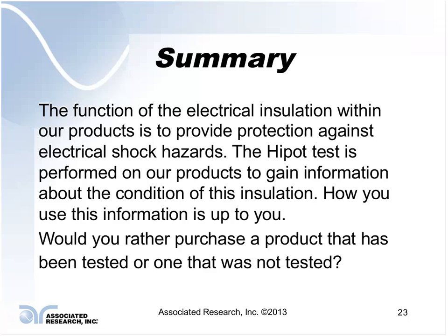It will tell you at what test potential the insulation did fail, if you actually ramp up your test potential. If you apply it immediately, with a 0 ramp time set up, or maybe 0.1 or 0.2 seconds, many times, because of the sampling rate of the tester itself, it may not indicate the test potential.